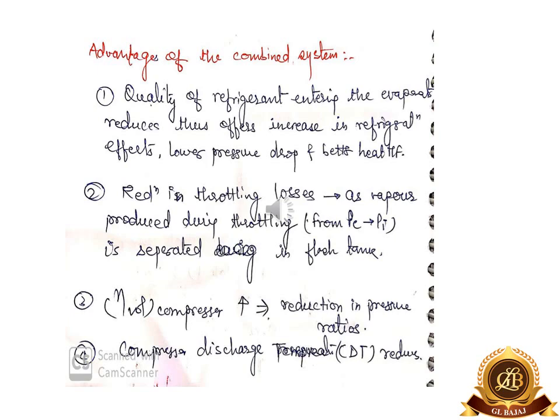Fourth one is that the compressor discharge temperature reduces. Because we now have a lesser compressor discharge temperature, we will have a better compressor life, and the lubrication will also be better.